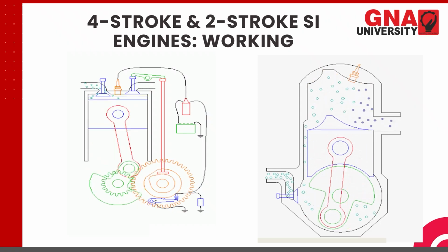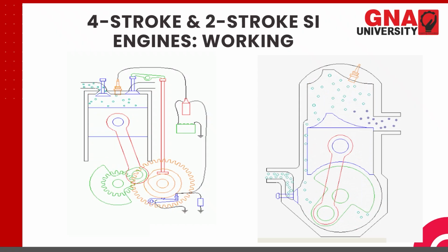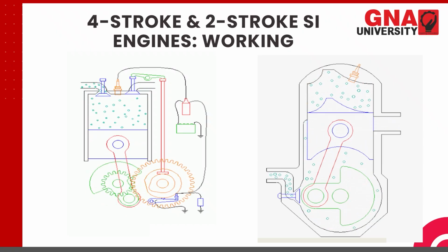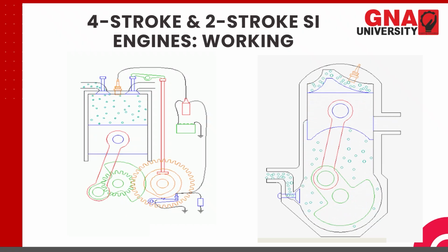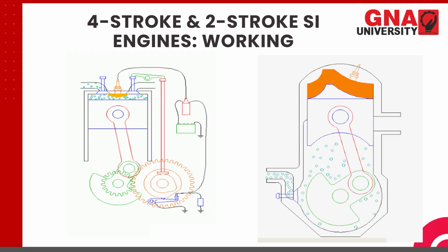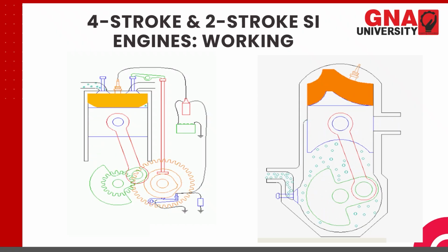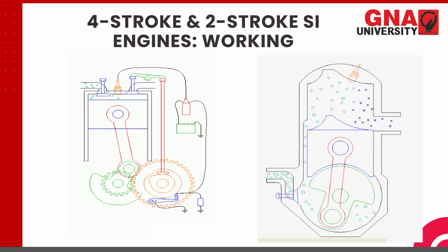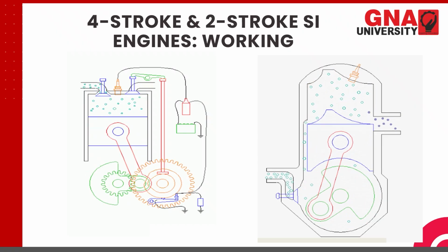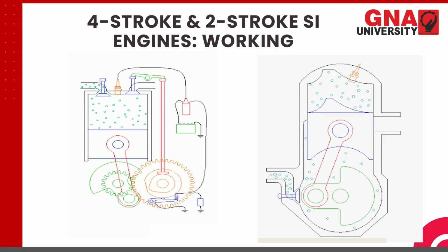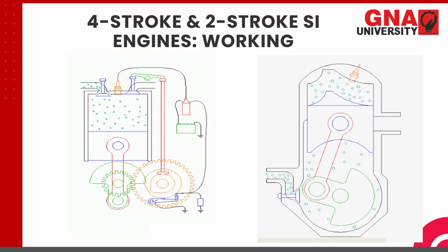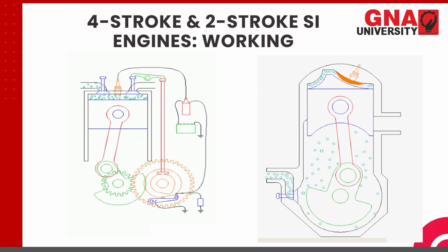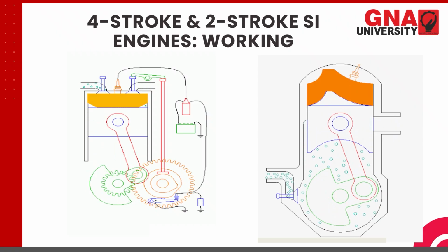Only in 2 strokes you want to open these valves, inlet and exhaust valves. So hence the cam rotates here. As the cam pushes this pusher rod, it moves this rocker mechanism and opens this valve. So this is the working of the complete mechanism of opening and closing of this exhaust valve. Both these valves remain in closed position with the help of the return spring.